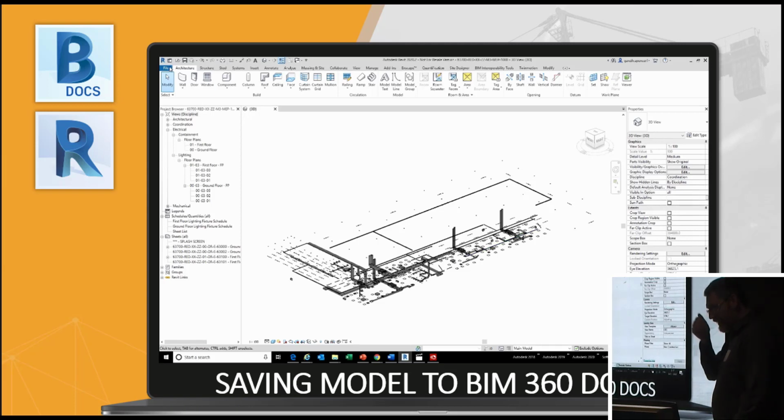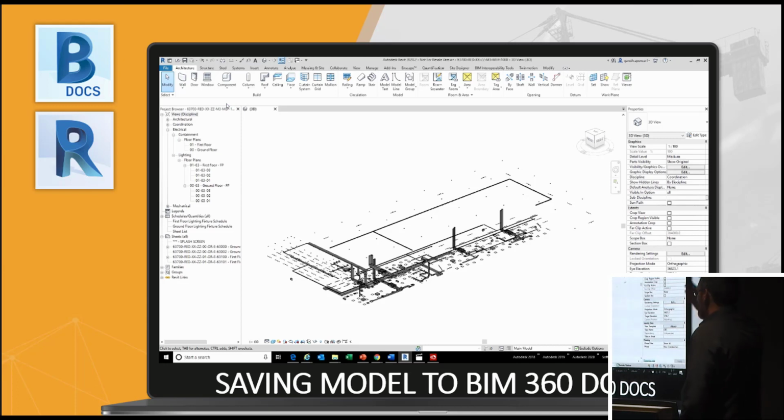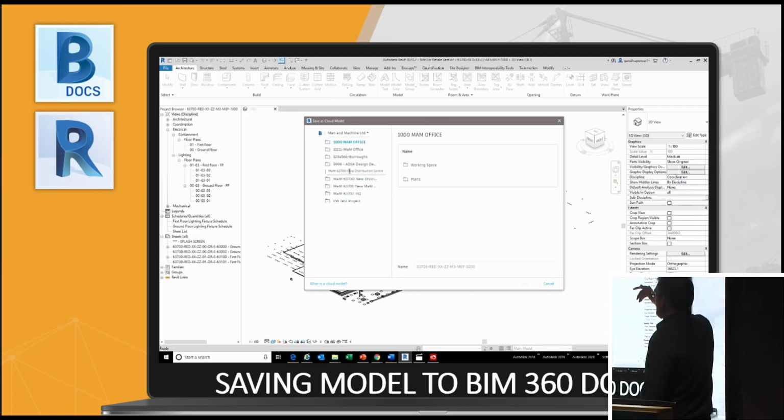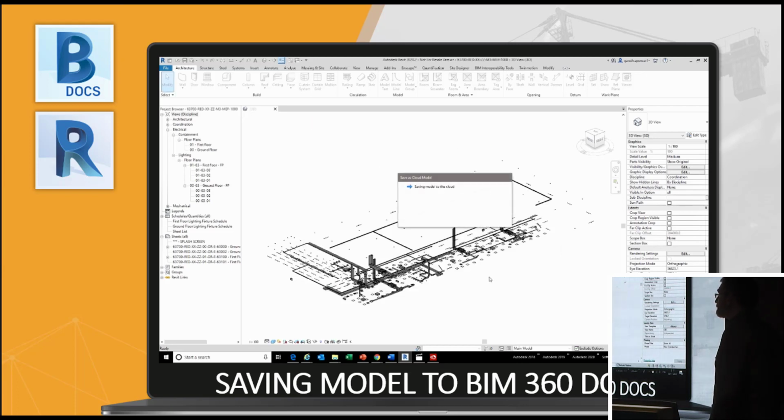And then from that, we're going to save our information to the cloud. So it's a simple file, save as, and cloud. Revit will do everything else for you. With regards to this, you'll set up your link to your hub, you'll use your desktop connector to connect it directly to your hub, you'll go to the location of where you need, and you simply just save the file in there. It's as simple as that.